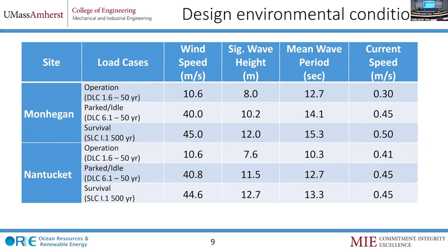Then survival is SLC, survival load condition 1.1. The requirement is a 500-year storm condition, as stipulated by ABS. Based on the buoy data, and using certain forecasting and joint probability models, we had access to all this information, which we then used for the purpose of this project.